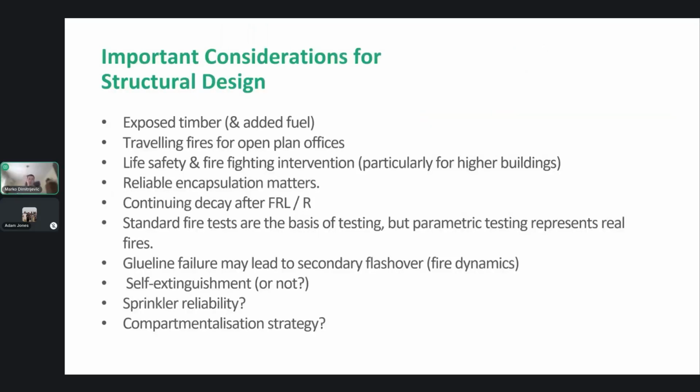It's good to first discuss the important considerations that we're going to talk about today, because there is a bigger picture involved than just structural fire design. There is a question about exposed timber and how much we can have of it, and that's pretty much the story for every timber project, and how different services interact with each other and how fuel is added. There is another open question about traveling fire for open offices, then life safety and firefighting intervention, especially as buildings are getting higher and higher.